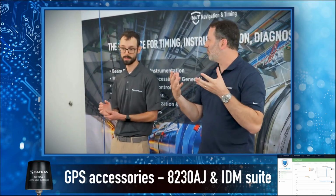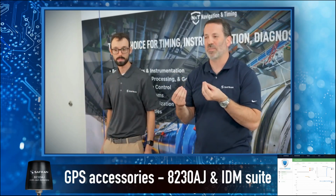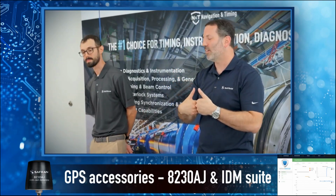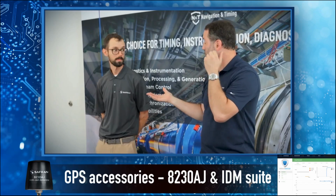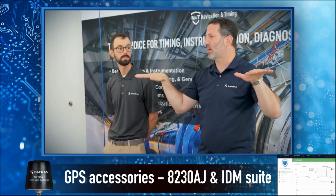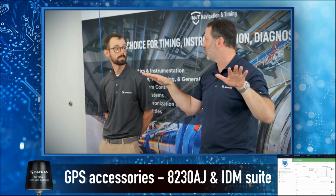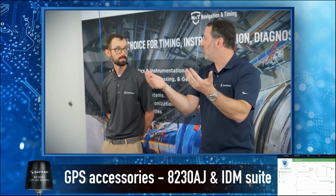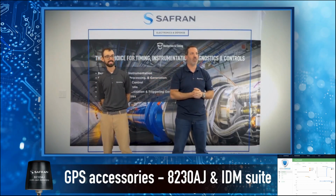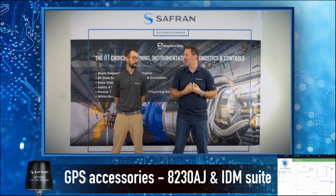Yeah, so you think of the AJ antenna. So the best way to prevent the interference is right at the source. Don't even let it come into the system, right? And the other piece that you explained very well, that you might hear the concept of horizon blocking, and that's really kind of what it's doing by doing that lower elevation filtering. But signal can still come in, and that's where the IDM suite comes in, because it can then do detection on the signal that's now come into the system, right?